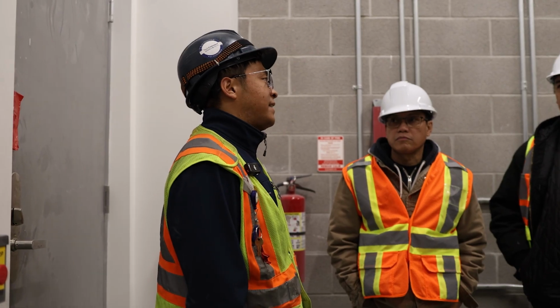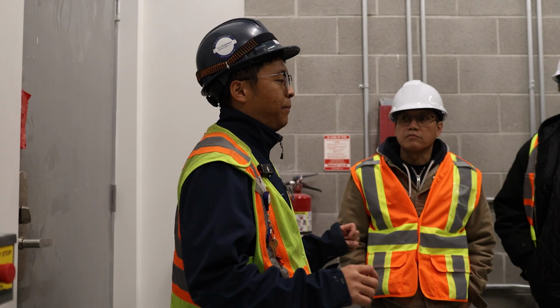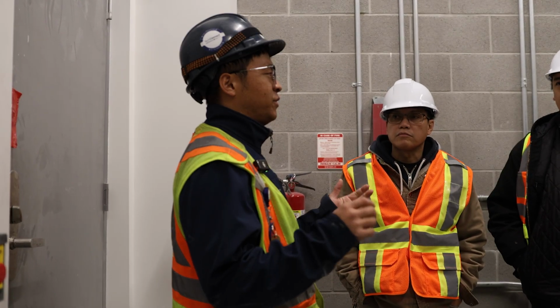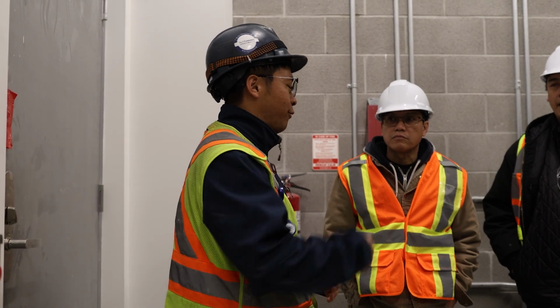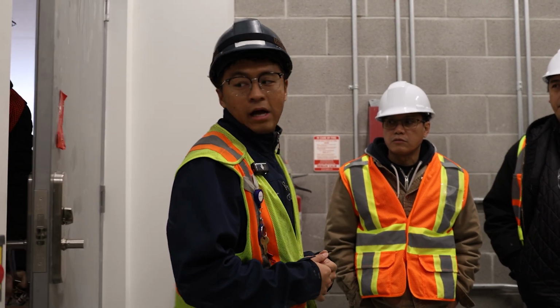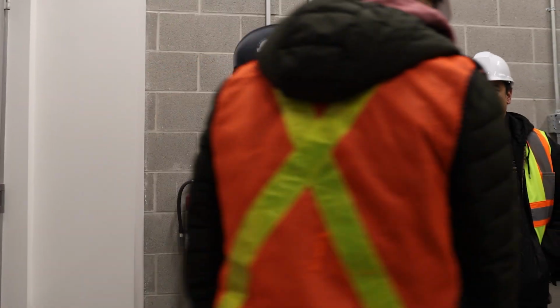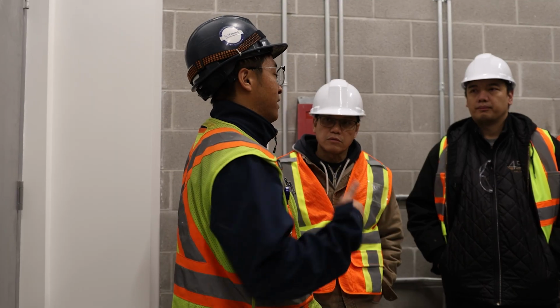Yes, we can set up the email alarm for you. So we can pick some critical alarms. Let's say, for example, some room space temperature we consider a non-critical alarm, right? That doesn't need to go to your email or your phone. And we can pick some critical alarms and set up the email alarm. And anytime the alarm triggers, the BMS will send the alarm to you.